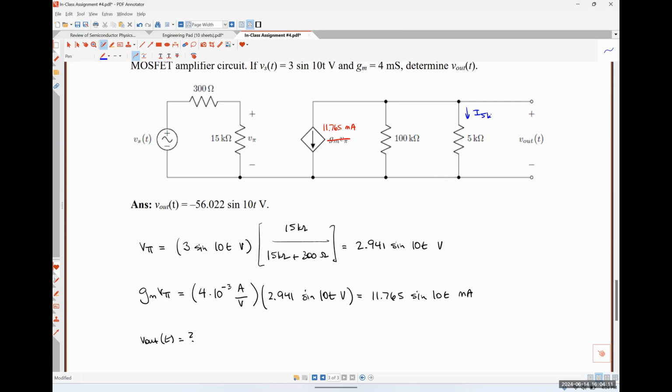I know this is going to sound weird, but the less obvious solution is actually to just use Ohm's law. So if we have a current and we have 2 resistors in parallel, the current times the equivalent resistance gives us the voltage that we're looking for. So we don't need to complicate things with current division in this particular case. It's not actually making things easier.